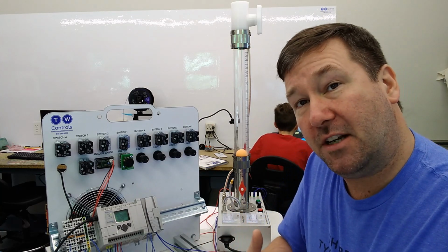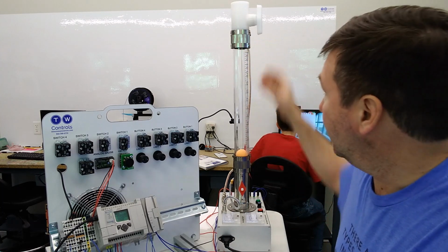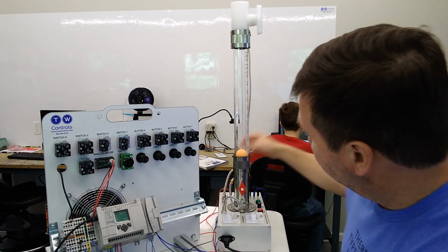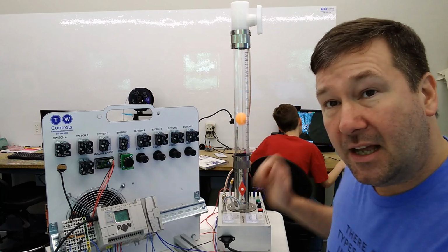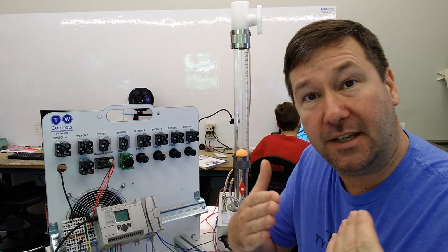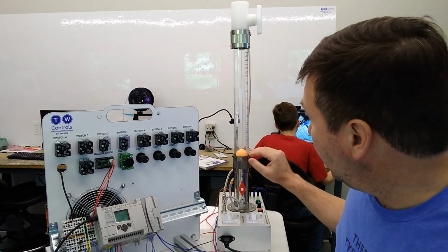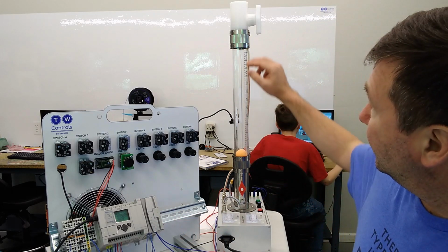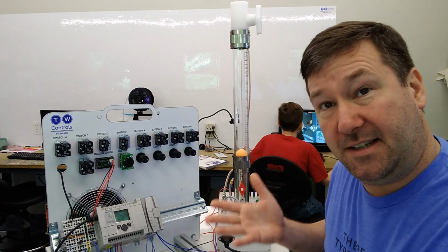The first thing we're going to need to do is scale this value here. We have a sensor up here that's looking at the position of this ball as it runs up and down, and right now it is just in raw units. Actually, the full scale is 0 to 16,383. What we want to do is get this into a value that we can interpret. We have our 0 value because it's sitting here right now.